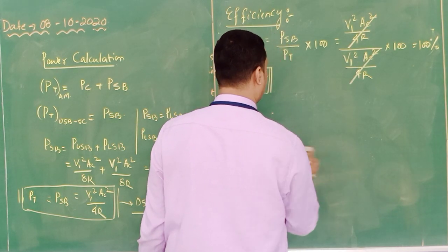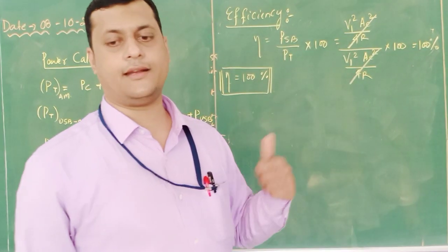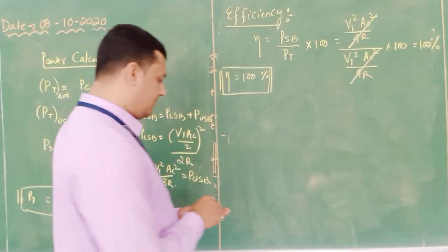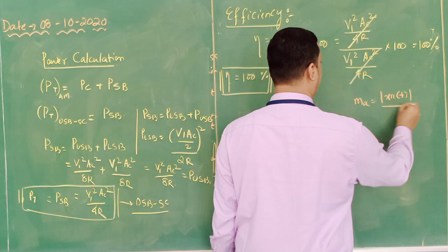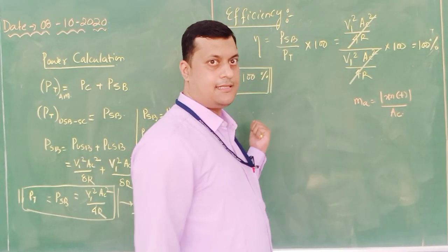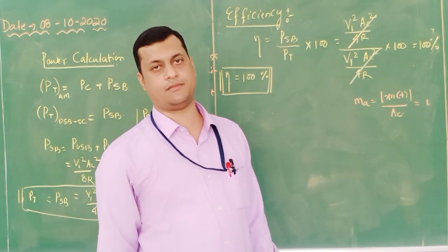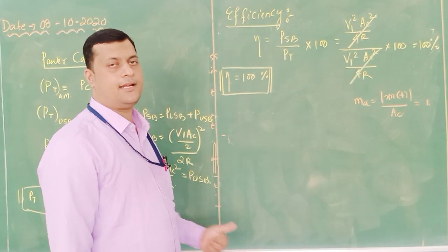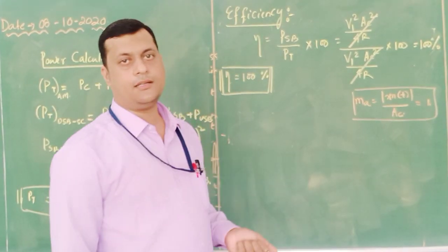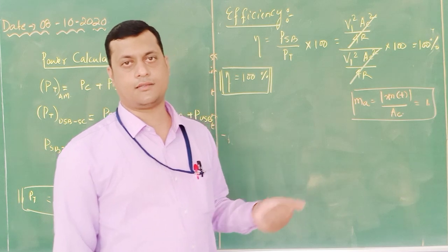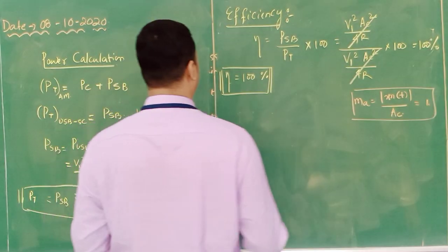One more important thing, here we are not discussing modulation index because here the effect of carrier is suppressed. So if the effect of carrier is suppressed, what will be your modulation index? Mod of m(t) divided by AC. So if AC is there and m(t) is equal, maximum critical modulation is possible. Because in DSB-SC we are neglecting the effect of carrier, the modulation index maximum value is 1. If it is greater than 1, the DSB-SC signal again loses the information. We cannot reconstruct the original message signal. Okay, so next we will discuss the multi-tone signal.